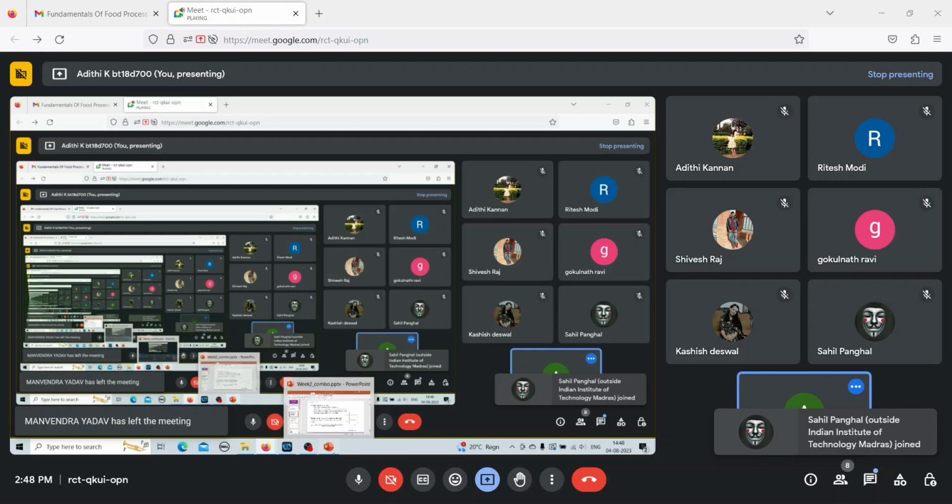Now, since the dynamic test is done to understand the viscoelastic nature of fluids, fluids that have both viscosity and elasticity, it will have a phase shift between these two. It will have greater than 0 degrees and less than 90 degrees for a real material or a viscoelastic material. It will be neither ideally elastic nor ideally viscous. So it will have something in between, between 0 degrees and 90 degrees. So the answer to this question is option B.